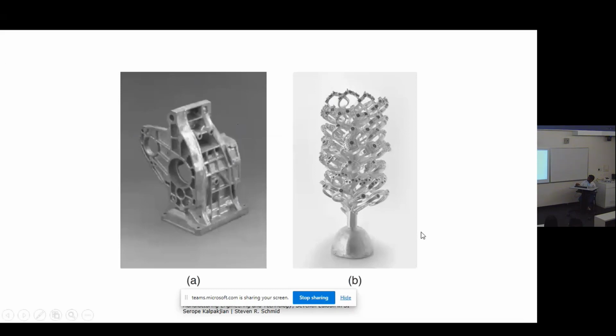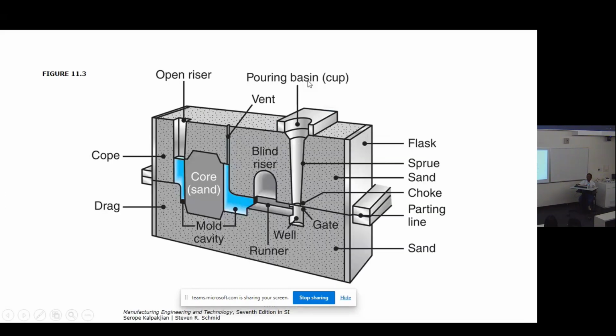So this is essentially a transmission housing made by die casting. You need a die to push the metal into a machine which has the die, and then the molten metal solidifies on the die. And then here is another one, a precision metal casting method. It also requires a mold, and then the rings are made using this. If you have any questions on that, let me know.